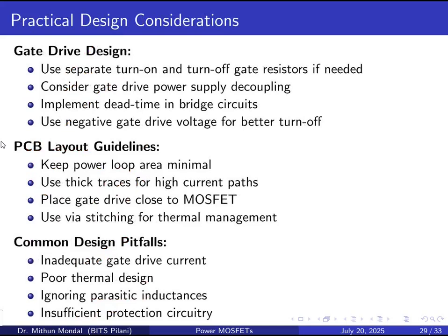Practical design considerations, we need to take care of the gate drive design, PCB layout guidelines, and common design pitfalls due to the different conditions, which can be due to the gate drive, thermal design, ignoring the parasitic inductances, and insufficient protection circuitry. So for practical purposes, whatever we do with the MOSFET will require proper care of the gate drive circuit as well as the layout design, and certain important design pitfalls can take place.